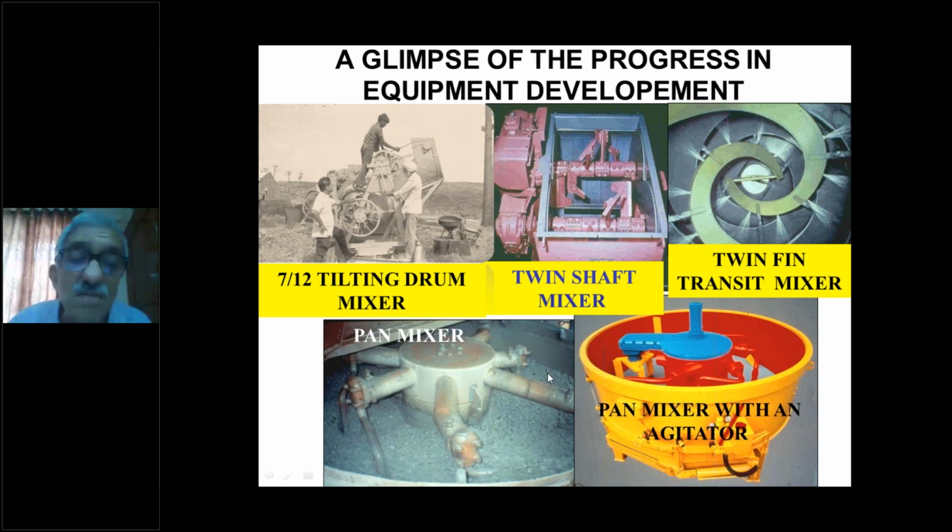The advantage of a pan mixer is that on the periphery, it has a water spraying arrangement. This is also available in the twin shaft mixers. It sprays water as indicated in the data you feed to the computer. Sometimes 50% of the water is added, sometimes the last portion is added. All depends on what you have fed into the computer.